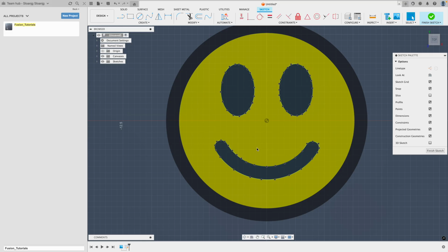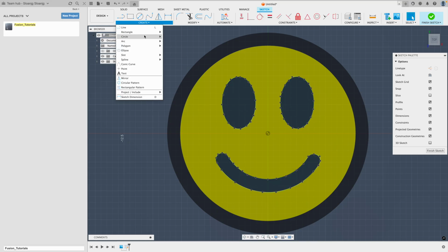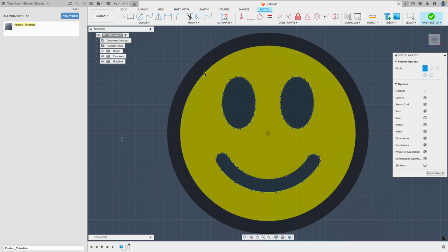And now for the circle, we want to highlight the edge of the coaster. Going to fit the screen here again. And here I'm just going to use a 2-point circle. I'm going to select one part of the diameter of the inner circle. Now I want to make sure I select the opposite diameter where the circle lines up along all the edges, moving it left to right. The graphic may be distorted slightly, and it's okay. Going to get close. That looks about close.